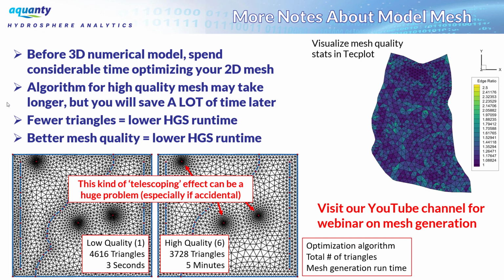I'll also just point out that if you're putting in a lot of polylines and polygons that aren't perfectly intersecting within your model mesh, you can generate these issues, this telescoping mesh. I think in these images, this is fine. This is actually by design because there are going to be pumping wells located at these nodes. But whenever you produce your triangular element mesh, definitely look throughout the mesh for any of these telescoping effects in areas where you don't expect them.